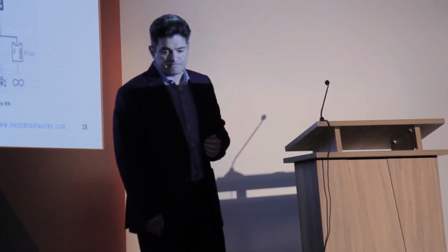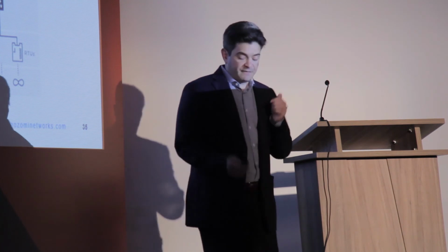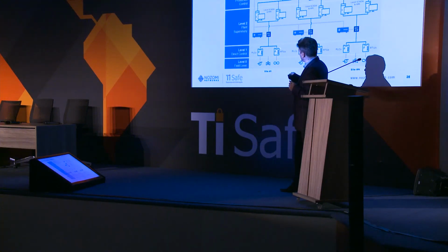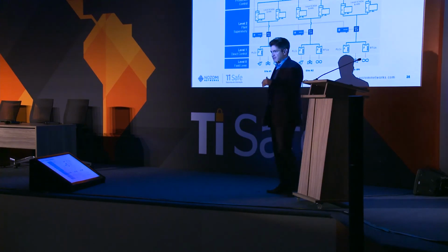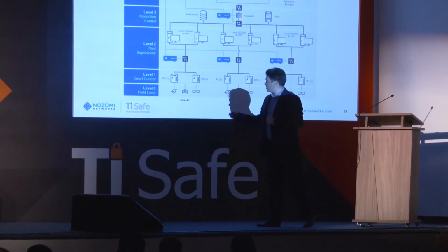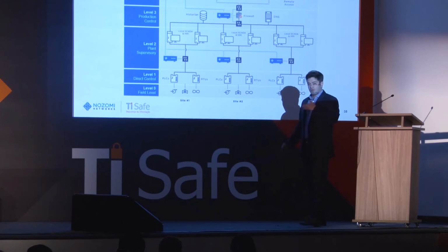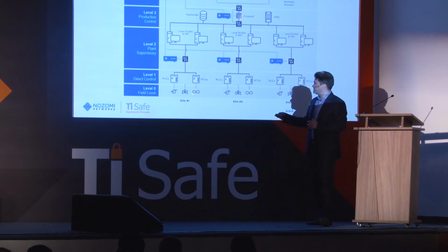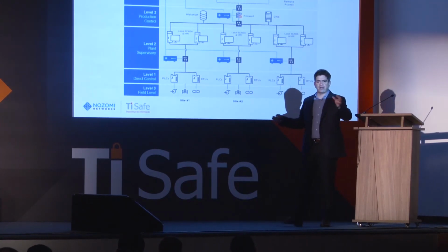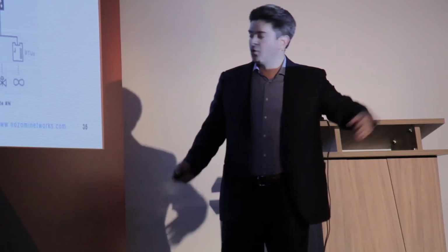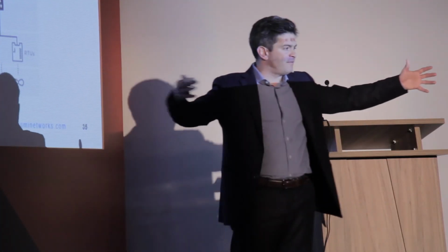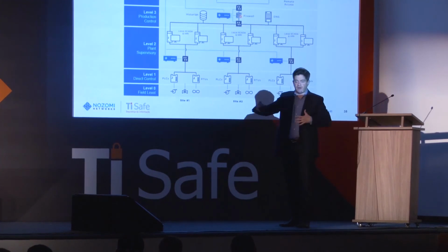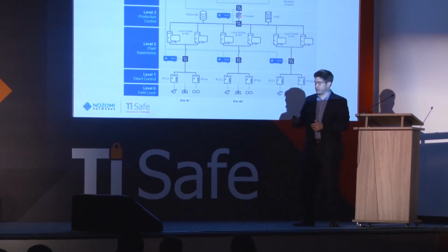These types of solutions tend to live deep in the network, so they are usually in between where your PLCs and your RTUs exist and the control network where your supervisory and control infrastructure lives. So you want to be listening to all this traffic. You want to go through a learning phase. You want to learn the physical process. You want to make sure that the solution works whether this site is super small, like a substation in the middle of the desert, or super large, like a network of 4 or 5 refineries together, sharing a common network with thousands of nodes.